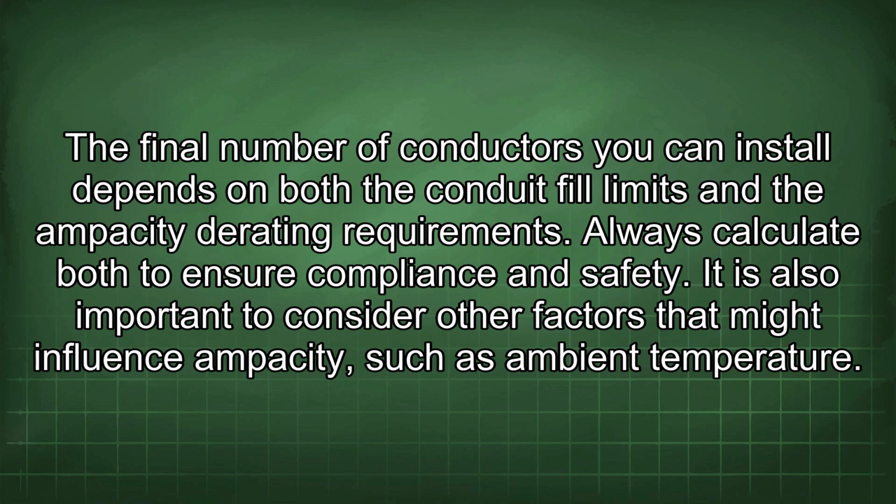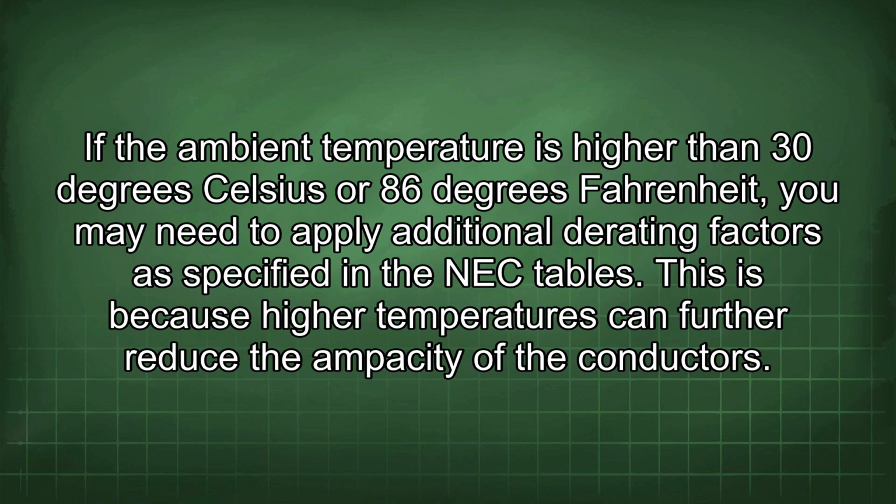It is also important to consider other factors that might influence ampacity, such as ambient temperature. If the ambient temperature is higher than 30 degrees Celsius or 86 degrees Fahrenheit, you may need to apply additional derating factors as specified in the NEC tables. This is because higher temperatures can further reduce the ampacity of the conductors.